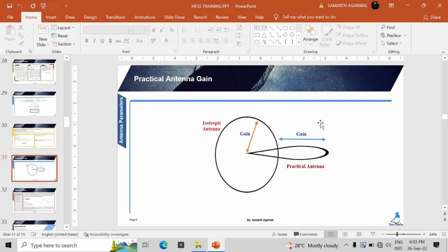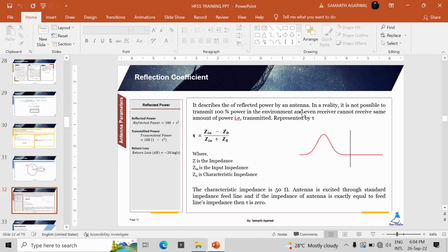So in case of dB, I am telling you we can measure in dB, and that conversion we can do in any way. But generally, in most scenarios, we measure it in dB only. 3 dB attenuation, you might have heard about. So that only we are considering in this case. So when we say 3 dBi, in case of directivity, it means with respect to the isotropic antenna we have 3 dB outside this boundary. Okay, so like that you can consider.